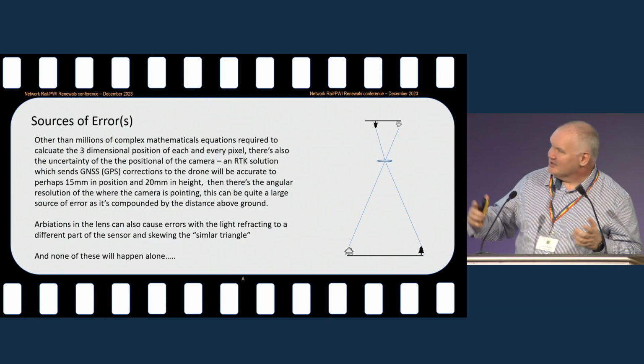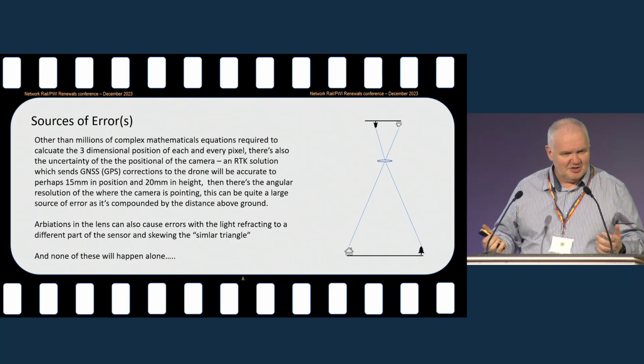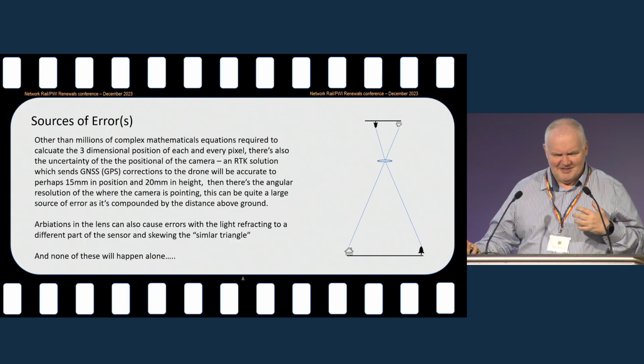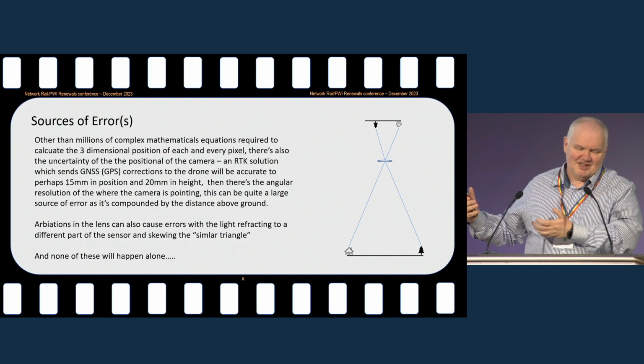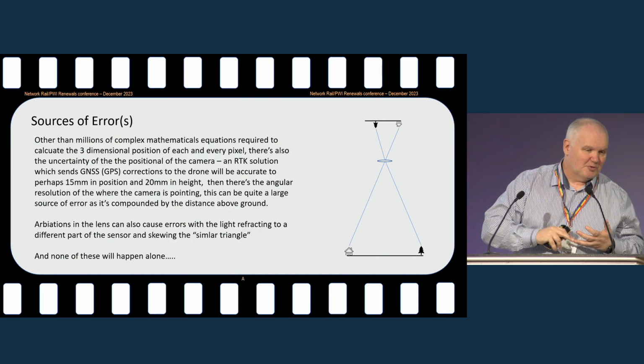So one of the other sources of error is that we're using drones. Drones are fantastic things. They're nice and light. But with the technology, there's a cheap drone and a dear drone; some drones are consumer grade, some are really high level. And depending on where you spend the money depends on your sensors, depends on your optical clarity.